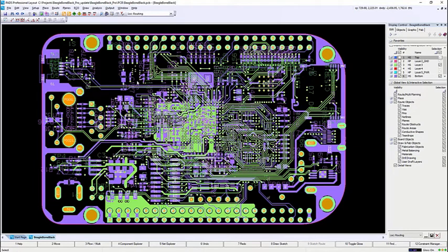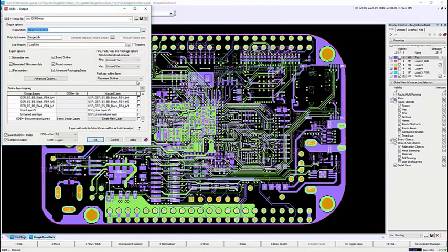Another common manufacturing output file format is ODB++. The ODB++ format represents the complete layout design for interfacing with Valor assembly and manufacturing tools and other third-party applications that accept ODB++. ODB++ outputs board data into a hierarchy, making it easy to manipulate.